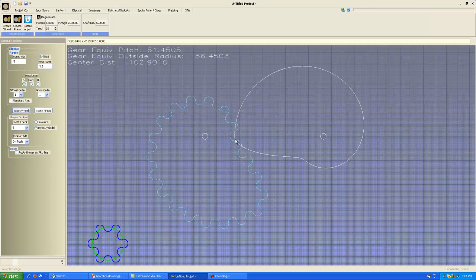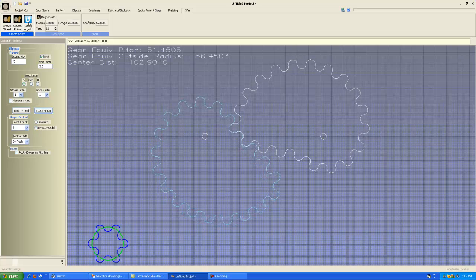Takes about 5 seconds, and as you can see, we did get a better shape by having a smaller shaper. So this goes to show that playing with the shaper parameters can sometimes help you when you're trying to tooth a very odd shape. And these two gears appear to mesh much better.